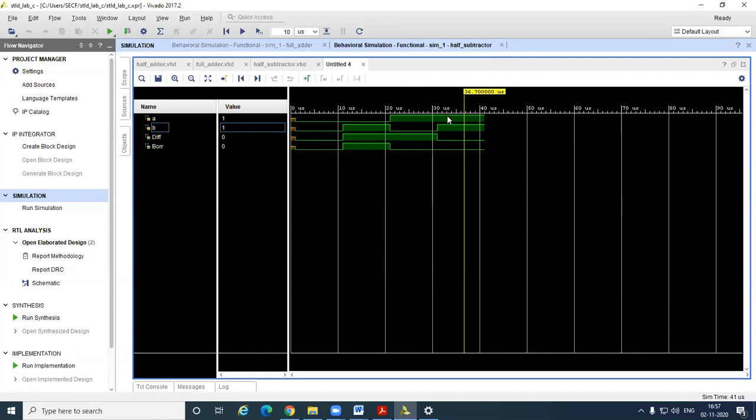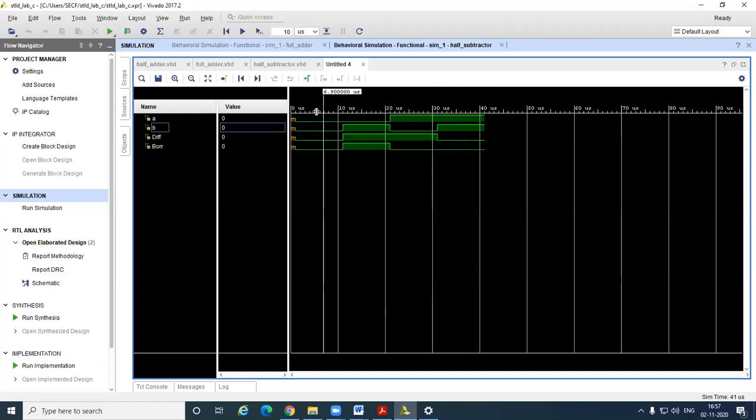The corresponding result is 0. If you observe the waveforms, the values corresponding to 0 are low. Observing, the first combination, 0-0, gives all zero outputs, difference 0 and borrow 0. Then the 0-1 combination borrow and difference values, the 1-0 combination difference and borrow values, and the 1-1 combination 0 and 0 values. This is the verification of the truth table.